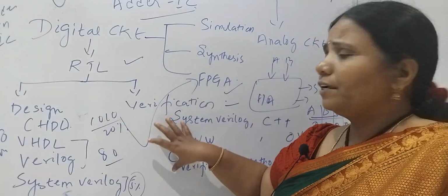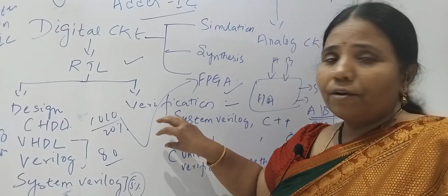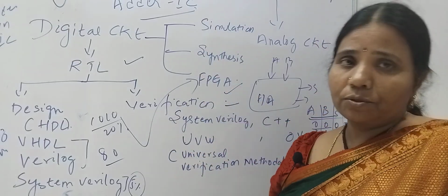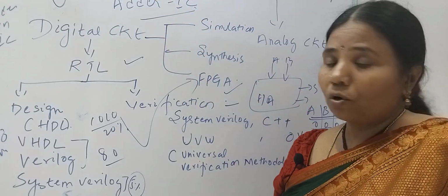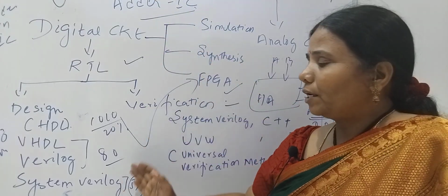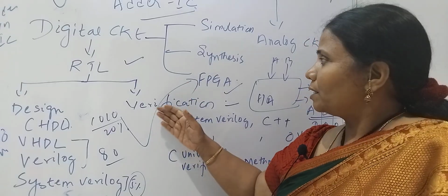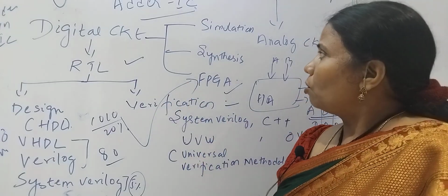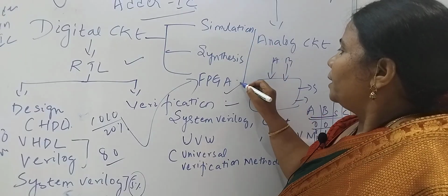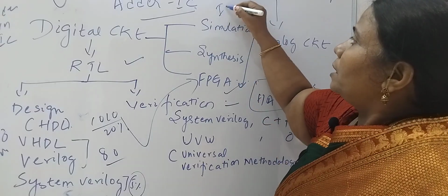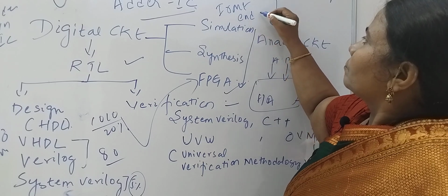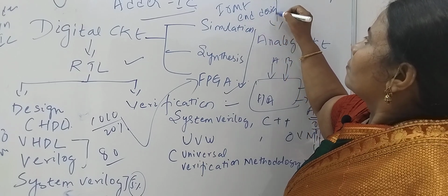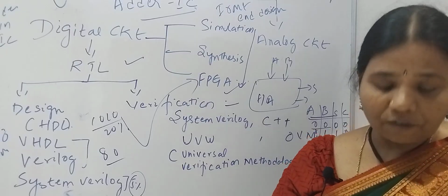In this way, the code developed and verified by giving inputs and outputs, which comes under simulation, then the synthesis gate level circuit you got, and the conversion of that code into a binary bit program of 1s and 0s on FPGA. All this design, from writing the code till FPGA, comes under the front end design of VLSI.